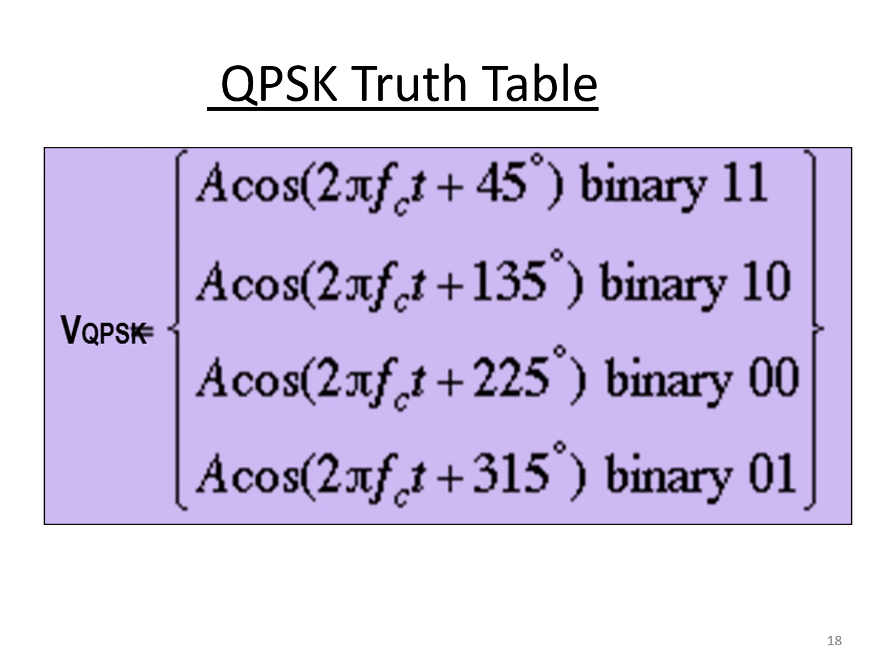Based on the given QPSK mathematical equation, we can see that when the input signal is 1, 1, the amount of phase shift in the carrier frequency is 45 degrees. For input signals 1, 0 and 0, 0, the amount of shifting in carrier phase is 135 and 225 degrees. For input 0, 1, the amount of shifting in carrier phase is 315 degrees.